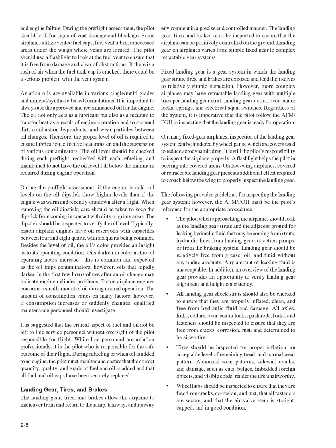It is suggested that the critical aspect of fuel and oil not be left to line service personnel without oversight of the pilot responsible for the flight. While line personnel are aviation professionals, it is the pilot who is responsible for the safe outcome of their flight. During refueling or when oil is added to an engine, the pilot must monitor and ensure that the correct quantity, quality, and grade of fuel and oil is added and that all fuel and oil caps have been securely replaced.